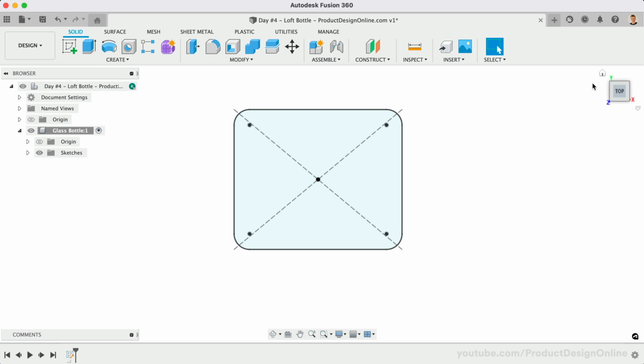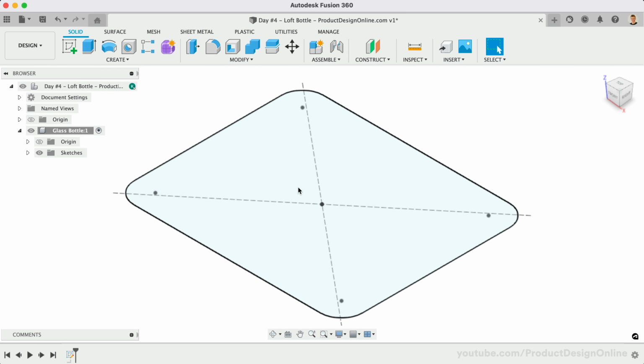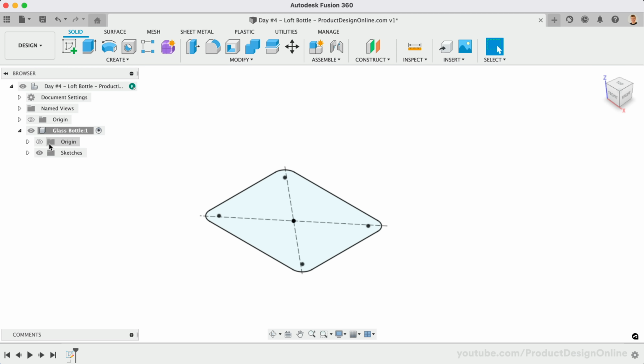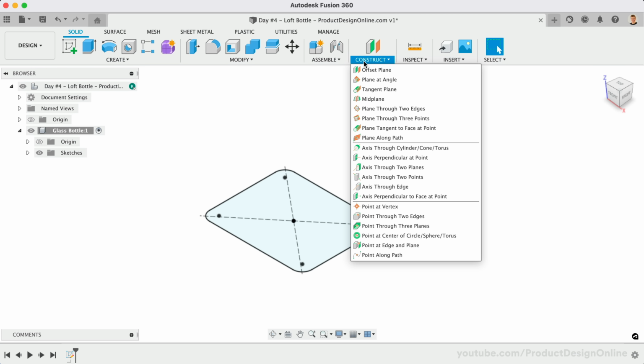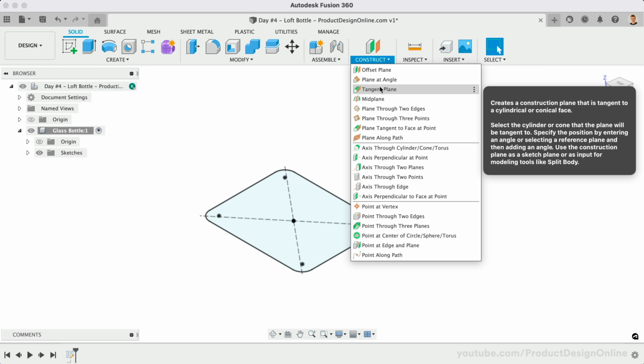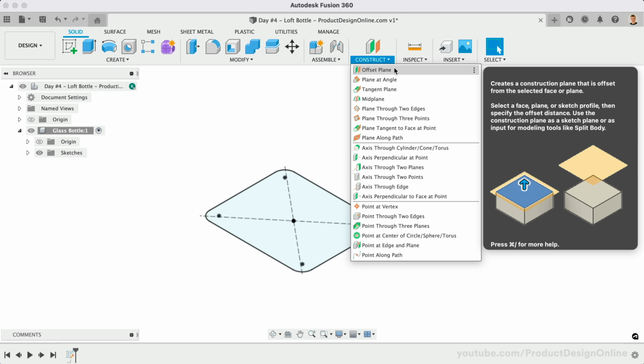Fusion 360 does not allow you to create regular sketches floating in space. All sketches must be started on an origin plane, a flat planar surface, or a construction plane. The various types of construction planes allow us to create a plane by leveraging existing geometry. Offset construction planes are the most common, as they simply require an existing sketch or planar face to offset from.